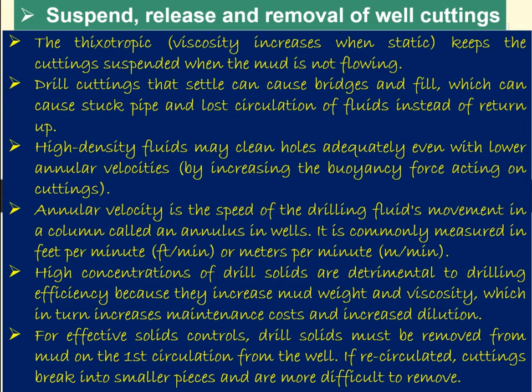Okay. So annular velocity means fluid injection rate, that drilling fluid can be controlled, regulated. No? So annular velocity is the speed of the drilling fluid movement in a column called the annulus in the well. It is commonly measured in feet per minute or meters per minute.